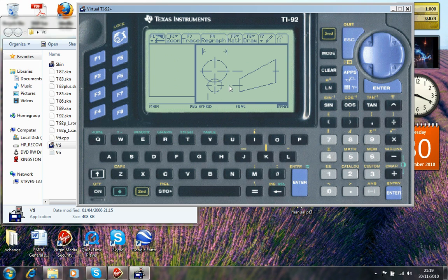layout. Here you can see the 2 views, the plan and the elevation for the oblique cone, and the cursor is flashing, prompting you for the base diameter. As you can see, the base diameter is the larger of the 2 diameters, so I'm going to enter 500 and enter. Top diameter, as you can see, top's the smaller of the 2 diameters, so I'm going to enter 250 and enter again. Now the cursor is prompting for the length. I'm going to enter 1000